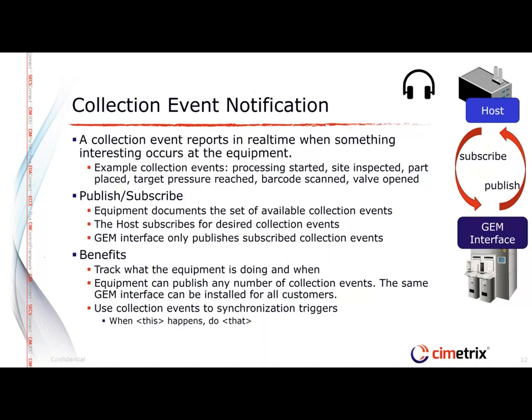So the benefit is the host can track exactly what the equipment is doing and when these things are being done. Another benefit is the equipment can publish any number of collection events. And you should be able to publish the same GEM interface to all of your customers because they're only going to subscribe to the ones they want.